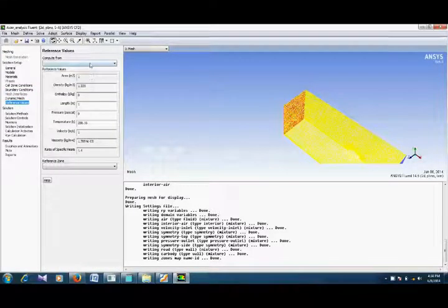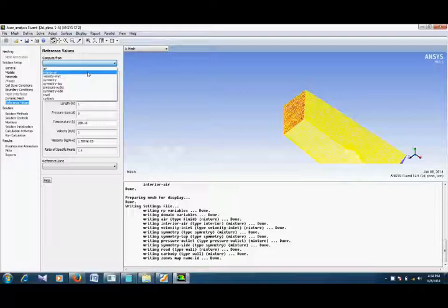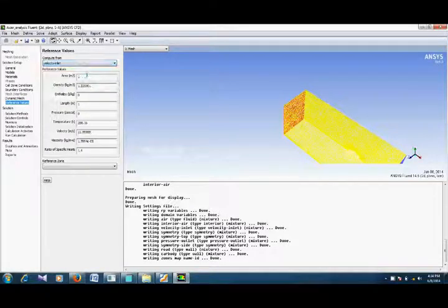Okay, after that we don't have any dynamic mesh. Reference values, this is an important one. It means that it will select that area of your car model for drag and lift calculations. So compute from velocity inlet, area, here it has taken by default as 1 meter square. You have to change it.